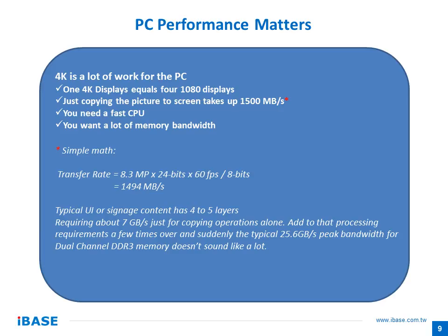And we can just do some simple math. Driving a 4K screen, that's 8.3 megapixels on the screen. Each of those pixels represents 24 bits of color data. We're doing that 60 times a second. That is about 1.5 gigabytes a second, just the video stream going out through that HDMI 2.0 or DisplayPort connector. Just that, nothing else.